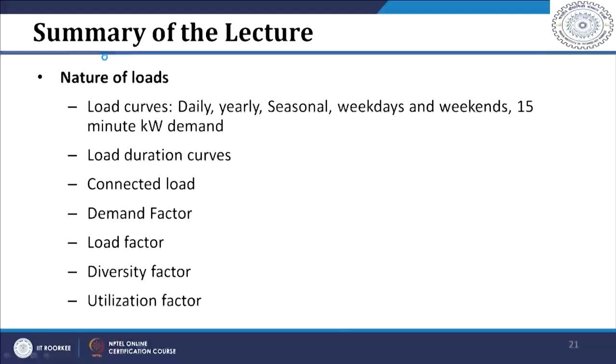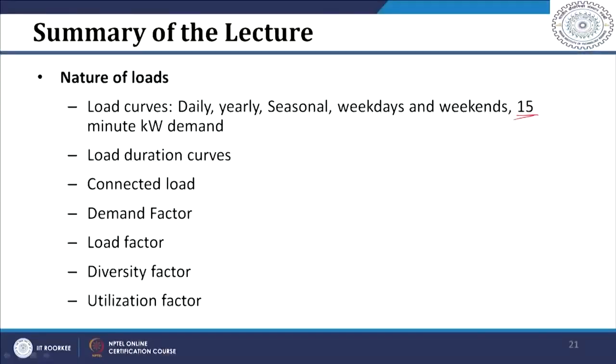So, in this particular lecture we started with different load curves, because we wanted to see the nature of loads. I explained what a load curve is, and we have seen that they can be plotted as daily, yearly, monthly or weekly load curves. Nowadays, with electronic meters available, we can plot a load curve called the 15-minute kilowatt demand load curve.